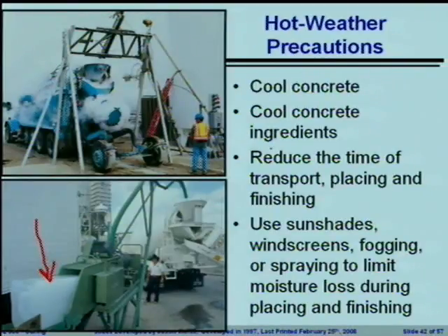They're cooling the ingredients. Here they're using liquid nitrogen. They may be actually just wetting the aggregate pile, using sunshades, screening the system. The basic idea is if you can cool down the aggregates, cool down the cement, cool down the water, you stand a high probability of making the concrete temperature much cooler.